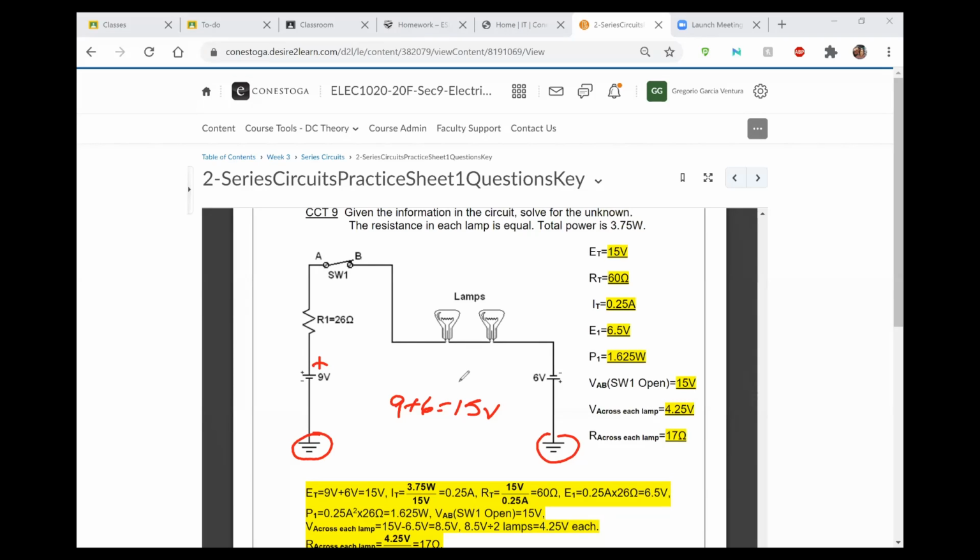So what was the question about that part that you were confused? I just was confused because it didn't look like a closed circuit. So because there's ground on each side, we're assuming the current's just going to flow through ground. Perfect. In large circuits, this is just for reference, in electronics you are going to see the ground symbol all the time, because you just cannot draw everything back to the ground with a line. So instead, on large schematic diagrams you are just going to have a ground symbol, meaning that everything is going to be connected back to the ground.